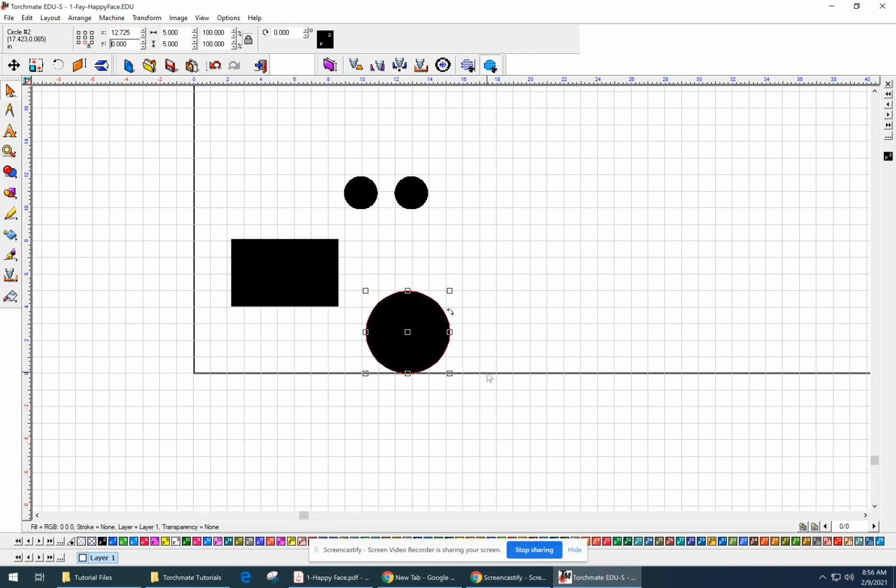That'll put it all the way on this bottom edge. Okay. And now if I grab this one and put its bottom node there, I want to go half that distance up so it intersects at exactly the halfway point, which is 2.5 inches.